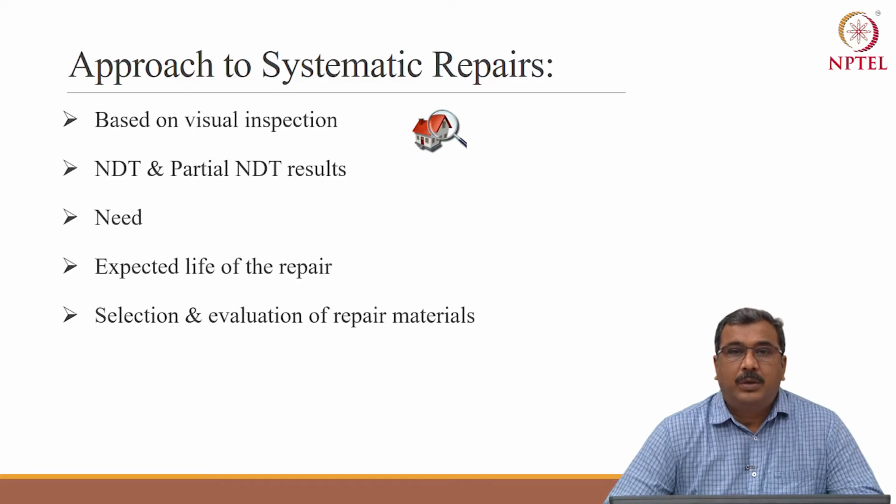You cannot use an epoxy grout for injection grouting for a leaking crack. Vis-a-vis, you cannot use a polyurethane grout for structural crack repairing. Similarly, you should not use polymer modified mortar for a large area and very high thickness. It is always good to go for microconcrete.